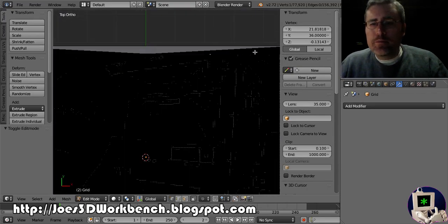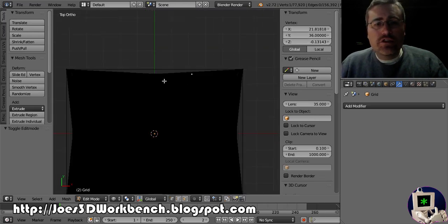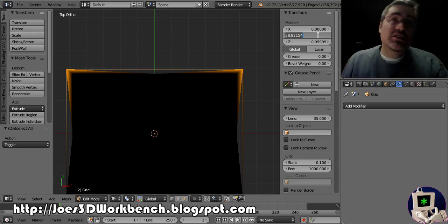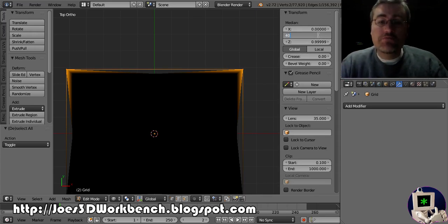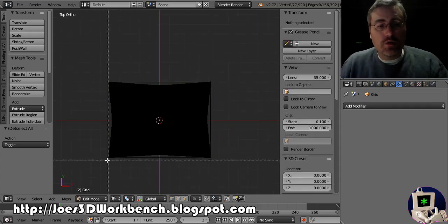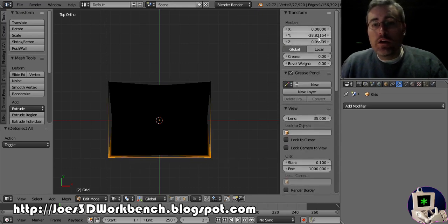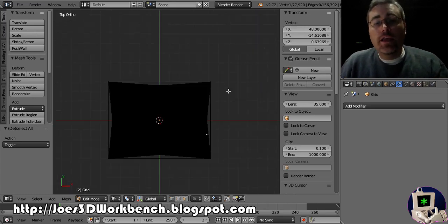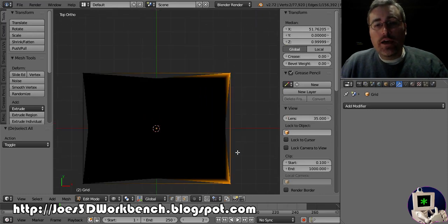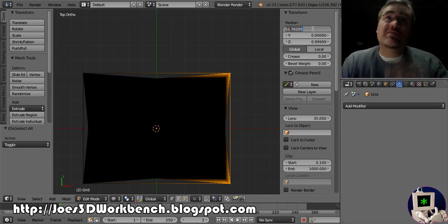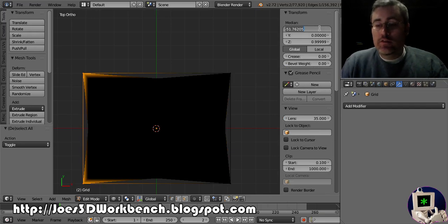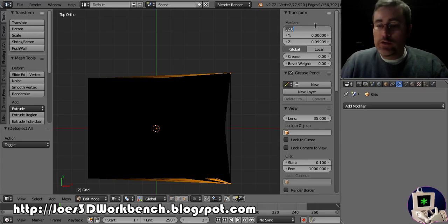They're the global points. That point is at 36 on the Y, so this point is going to be at 38, 40. Yeah, 4 millimeter stick. That'll work. Do the same with these points at the bottom, negative 40. These points are at x equals 48, so these points are going to be at x equals 52. Yeah, so it's 4 millimeters on the side. 52. Nope, negative 52, negative 52, negative 52.